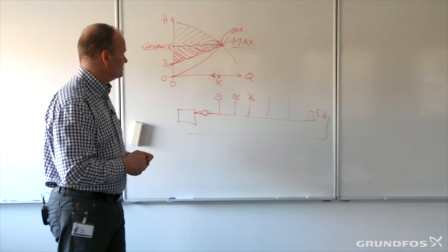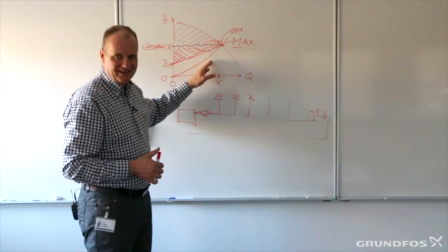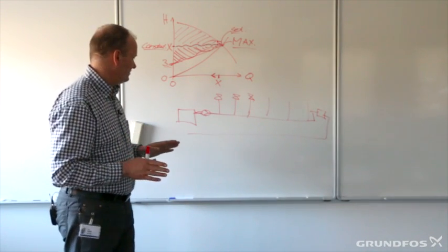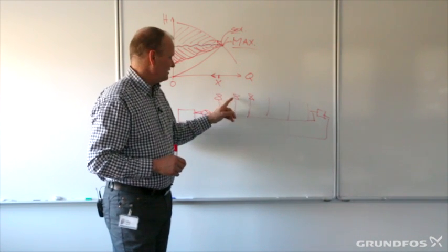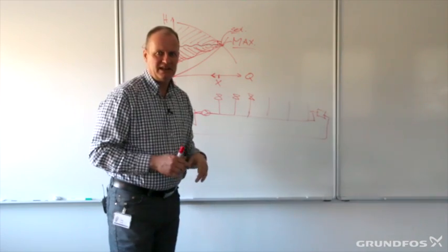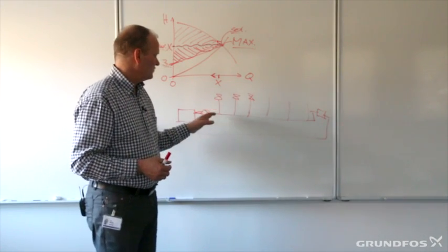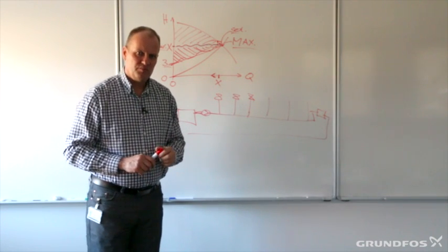So that's a huge benefit to the use of energy for the pump. But also one other very important element is that the stress on the dynamic valves and other vital equipment is going down while we are operating the system with a speed control pump.